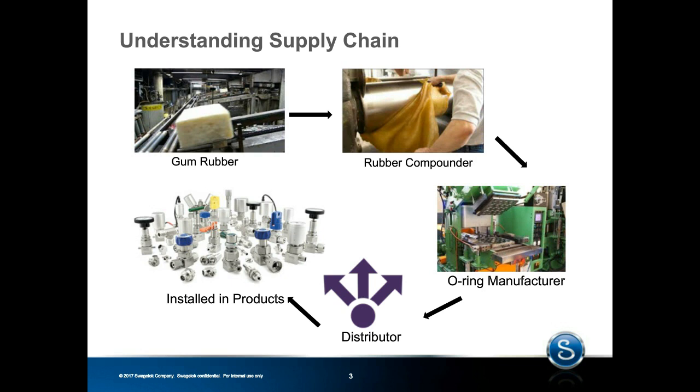recipe for that material. So a lot of times I hear engineers incorrectly referring to the elastomer material as resin or what grade or what lot. And all of that sort of creates the start of the communication problems, because what you need to be referring to is a compound and a compound number, which is a specific recipe for a seal material that you may be using.